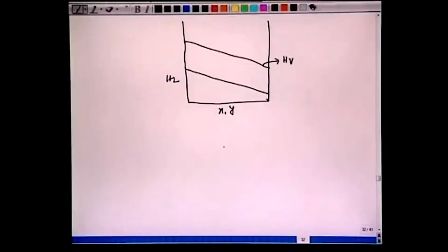Okay, now here, as we said, anywhere on this HXY diagram, we can take two streams. We chose P and N. In the earlier example, both were superheated vapors, so we mix the two. Our third component, the new mixture, will have the enthalpy which will lie on this straight line. This is how we got the equation of the line. This is true anywhere on these 2 points, which means now if we choose, say, C, all right, and draw any straight line here, say it cuts this curve on E and this curve on D.